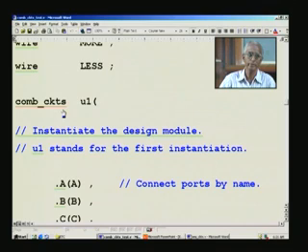So, when we call, what it means is when you convert this into an actual working circuit as an IC chip as such, then this circuit will actually function because of this statement, right. So, you have to instantiate here. Whatever is the design module, you have to call that module, that is known as instantiation here, and you just put that particular design module name, that is all. Are you clear about it? So, this is different from the test bench. We had declared a module called the combination circuits underscore test, but whereas we are calling the actual design only here, and this you can call any number of times.